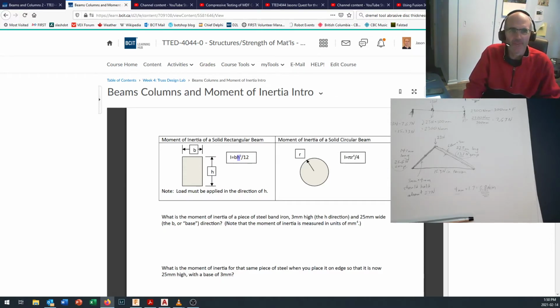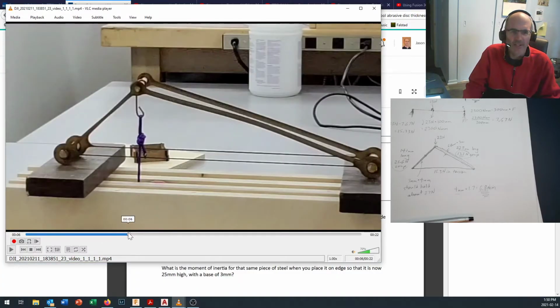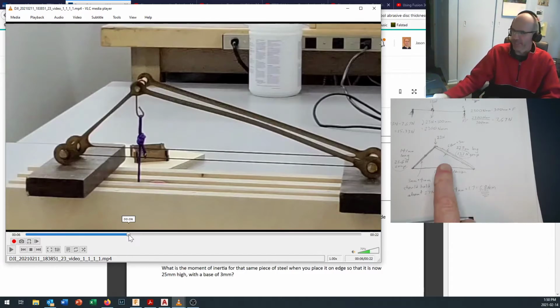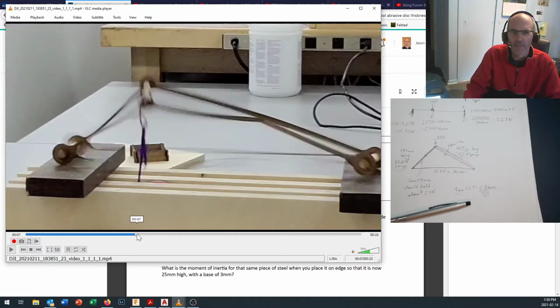Then we went and we did some tests. And what we saw was that we actually got this structure when I did my initial tests. Like I say, I couldn't get it to hold 10 pounds because I was hanging the 10-pound weight off of it. And so it didn't meet these loading criteria. But that was because the weight was swinging back and forth. And so watching carefully what's happening can tell you a little bit about your structure. With our new jig where the weight is applied perfectly vertical and you get a chance to get it perfectly centered right on there, we saw it fail.